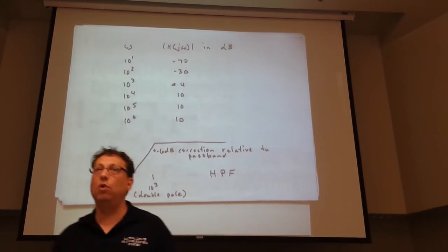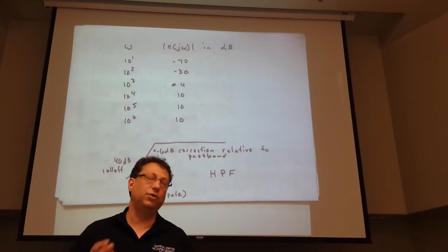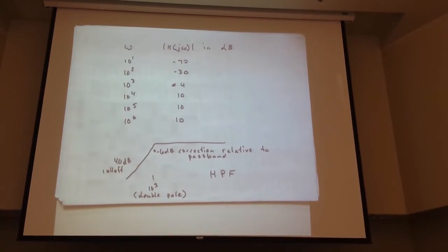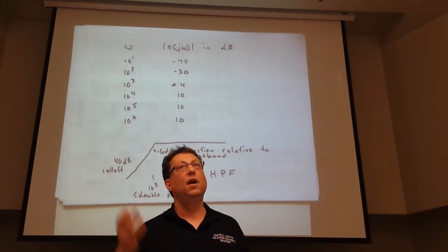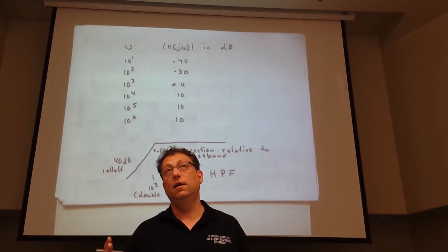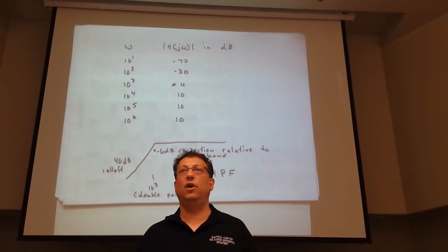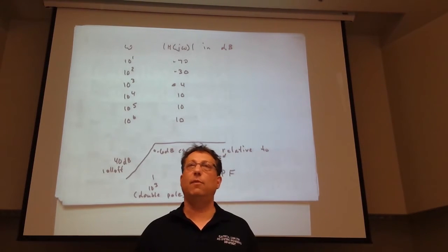When I say a complex pole, I'm really talking about resonant frequency as opposed to real numbered poles. So resonant frequency is a real number when we have an underdamped circuit, rather than talk about the poles directly, which are complex. I want to bring this up again because I've had a bunch of people ask me. If the circuit is underdamped, there are still 2 poles in it. They're complex. So rather than look for complex points on a real curve, we look at the resonant frequency and consider that our double pole.